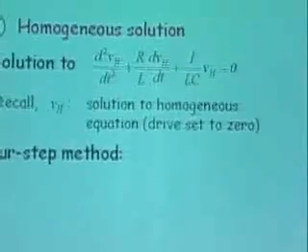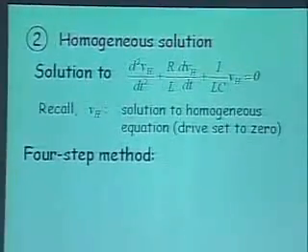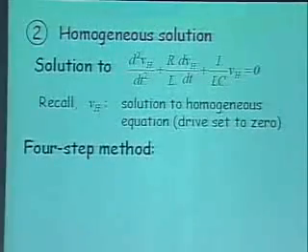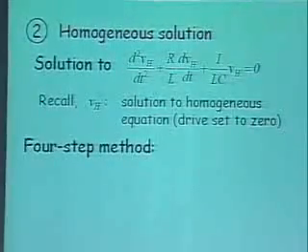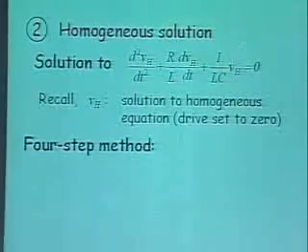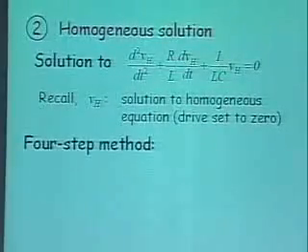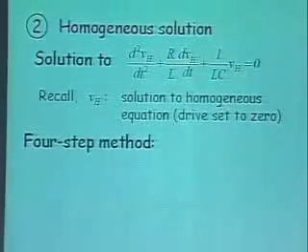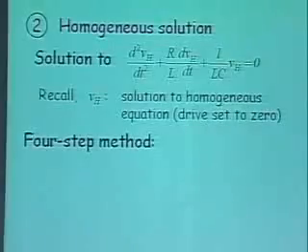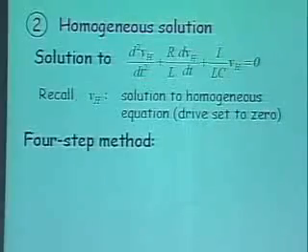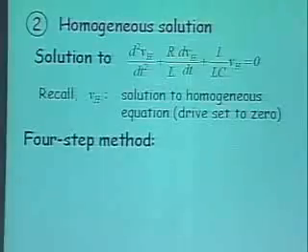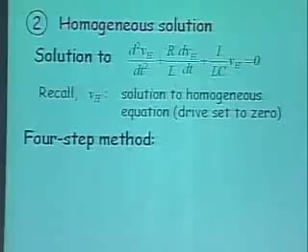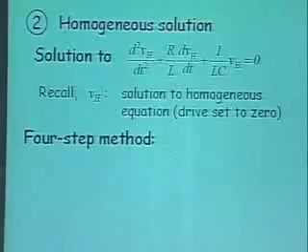Simple. Second, I go and do my homogeneous solution. And the homogeneous equation, remember, is the same old differential equation with the drive set to 0. Remember that sometimes this equation with the drive set to 0 is the entire equation you have to deal with, in situations where you have 0 input, for example, or in other situations in which you have an impulse at the input. And the impulse simply sets up the initial conditions, like a charge on the capacitor or something like that.